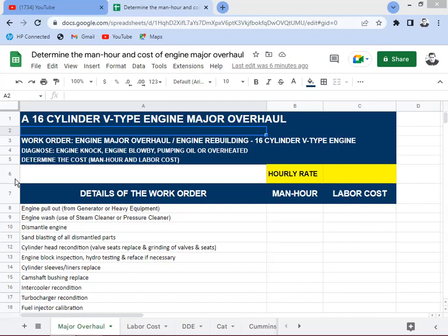And also engine blow by. Engine blow by is when you have combustion on top of the piston in the cylinder, and instead of having a good compression cycle of the engine for combustion, the pressure that is being compressed is leaking through the piston rings, around the pistons.